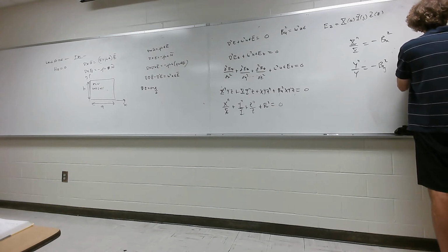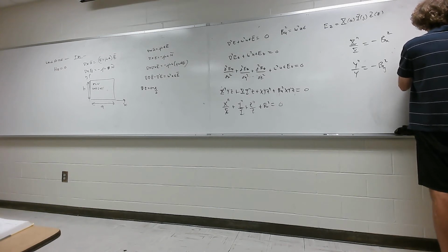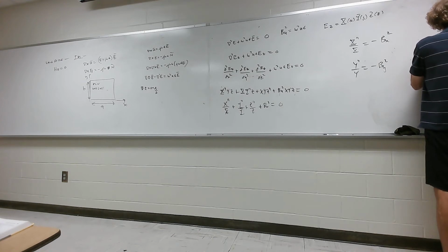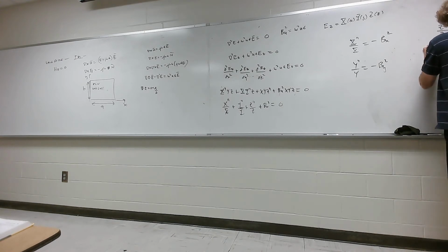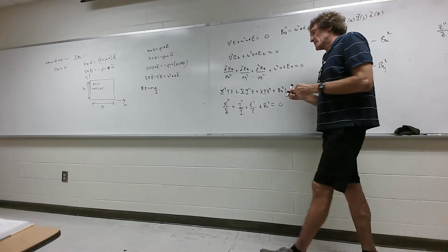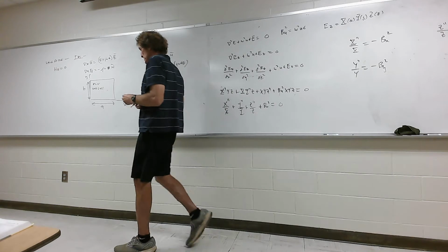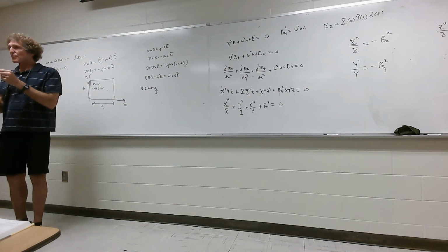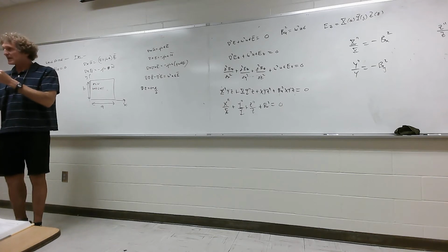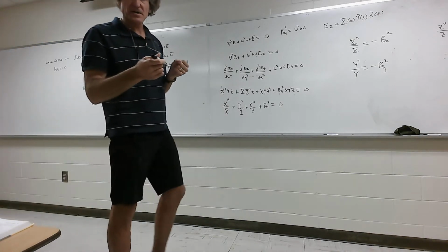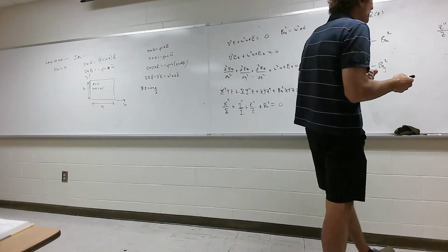When I have z double prime over z, I call that minus beta z squared. Wentworth's book just calls that minus beta squared. He drops the z, because beta to him is the beta that has to do with propagation in the media or in the guide. So this is actually beta sub z, but he doesn't put the sub z on it. I do. That's the only difference.